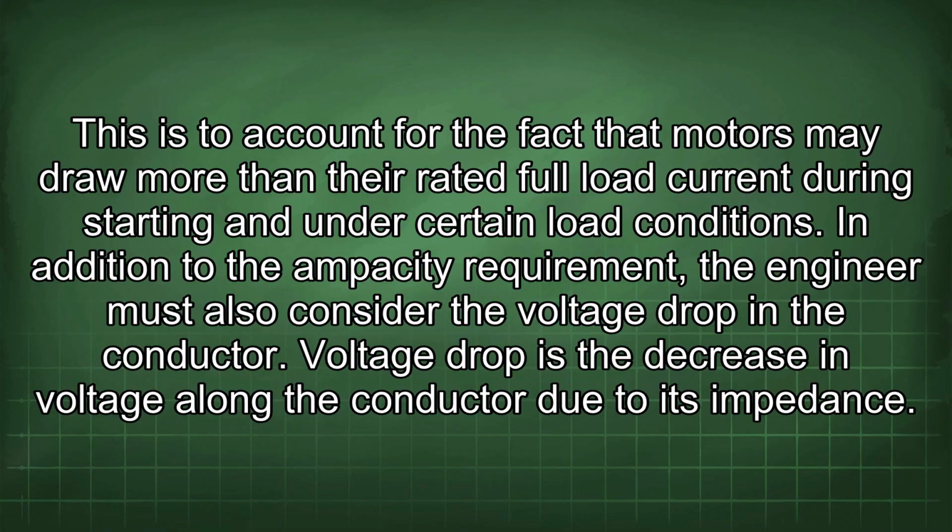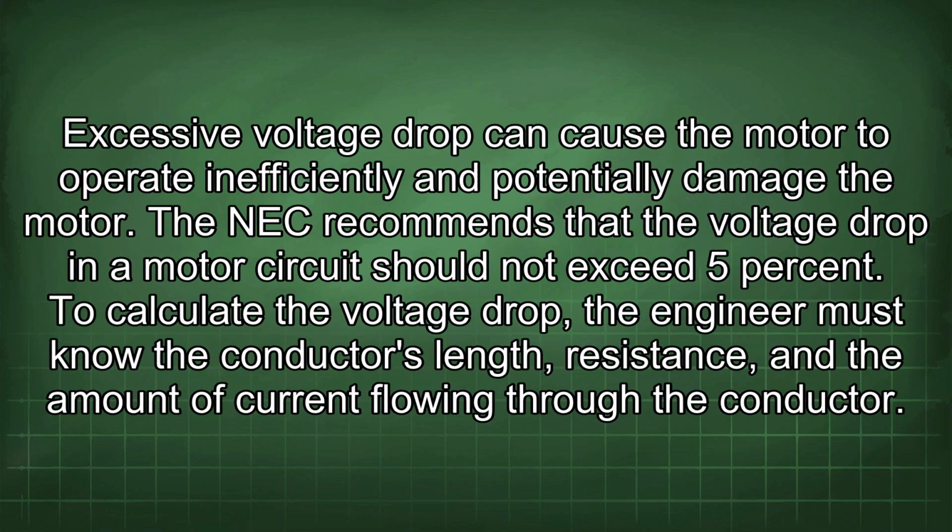In addition to the ampacity requirement, the engineer must also consider the voltage drop in the conductor. Voltage drop is the decrease in voltage along the conductor due to its impedance. Excessive voltage drop can cause the motor to operate inefficiently and potentially damage the motor. The NEC recommends that the voltage drop in a motor circuit should not exceed 5%.